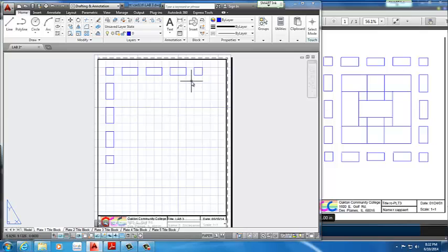So I'm going to change the X spacing, and I want to copy it to be a quarter inch. So I'm copying it, let's say from this point, and that should automatically change to this point here. So take all of these, 0.25 Y spacing. And how do you get the copy pattern from here to here, because that's exactly where I want all of them to go? You have to tab to place them.